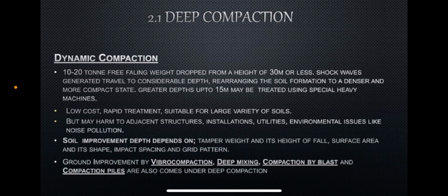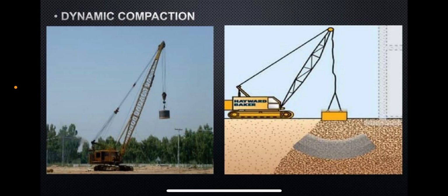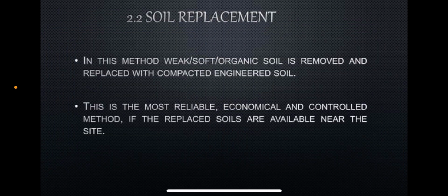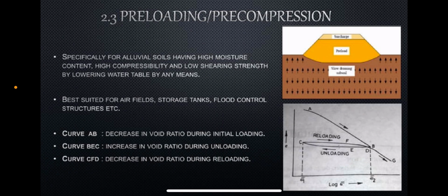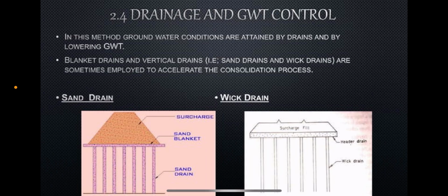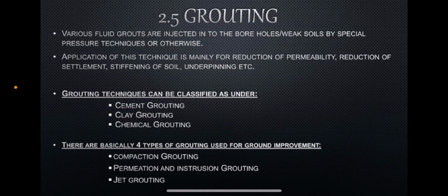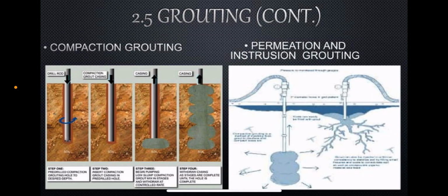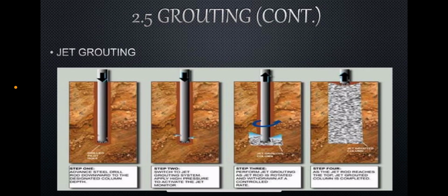And these are the techniques for subsurface stabilization: dynamic compaction, soil replacement, pre-loading, pre-compression, drainage, GWT control, and grouting. And this is the grouting technique. Normally we use grouting techniques underground. We grout the underground and stabilize the soil. This technique is the most familiar technique.